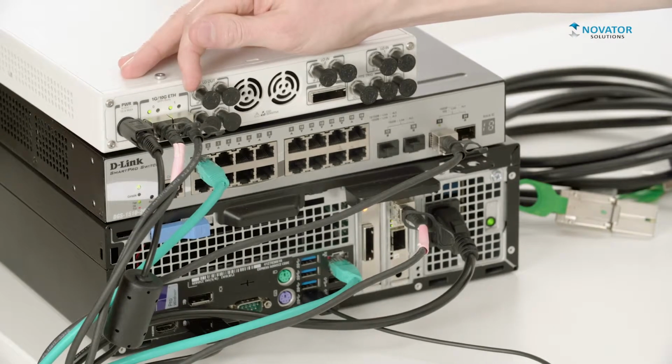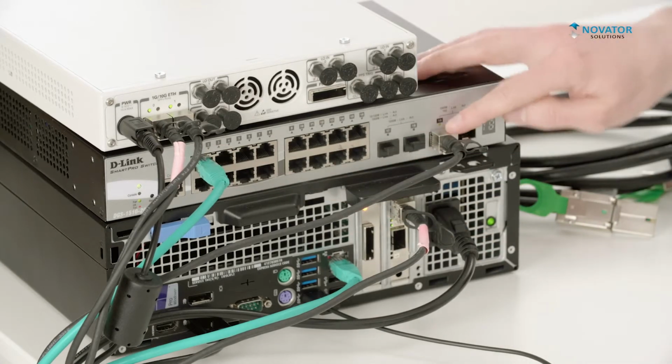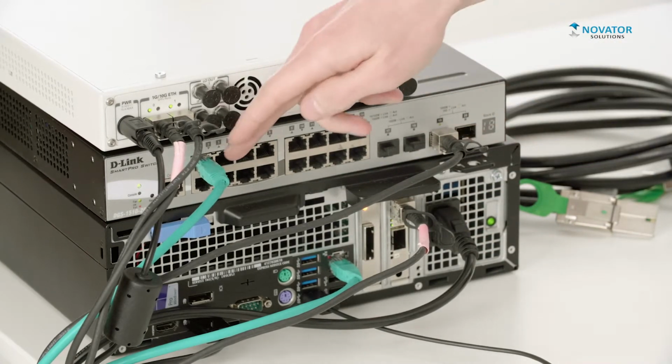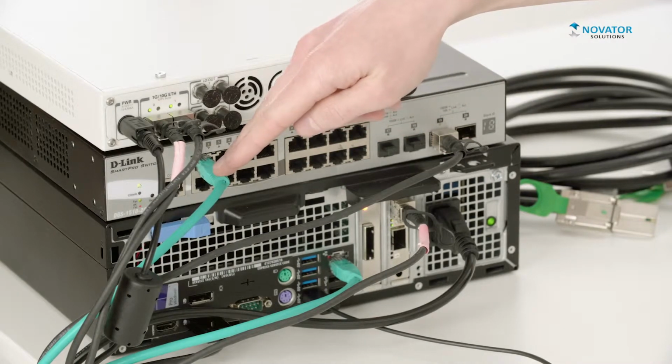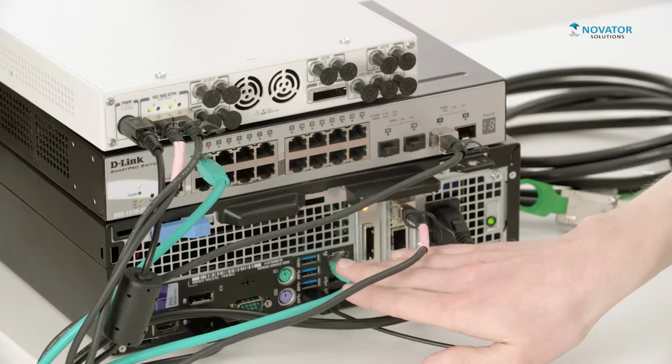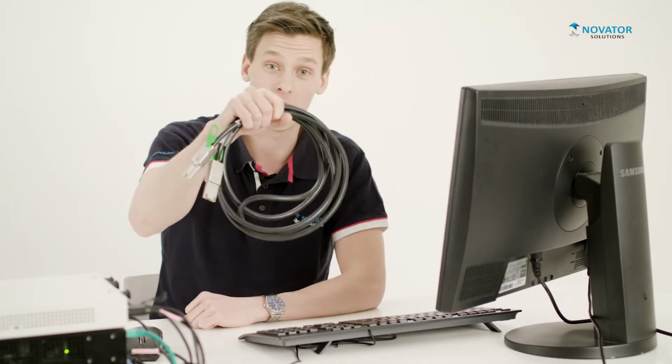The second port is dedicated for streaming channelized data. And this is connected to the switch, which enables channel data streaming to multiple clients. Today we have it connected with a regular 1 gigabit Ethernet cable to our network card on our desktop computer. If you bought the USRP 2955 from Novato Solutions, it comes pre-installed with the correct firmware. Otherwise you would need this MXI link connected to this PCI Express port to update the firmware.